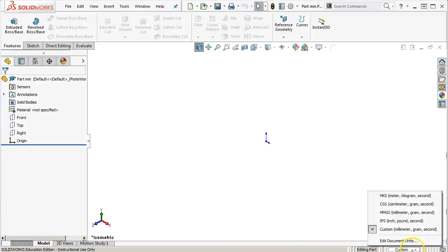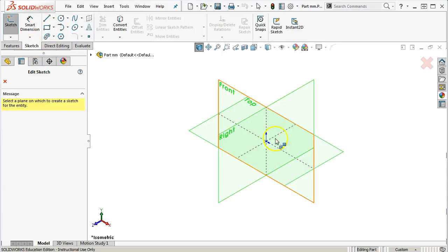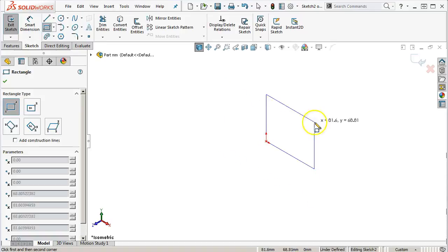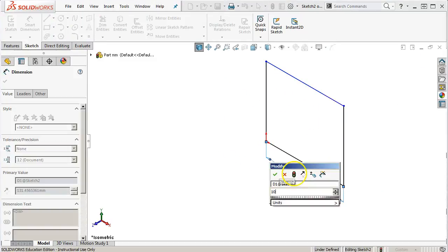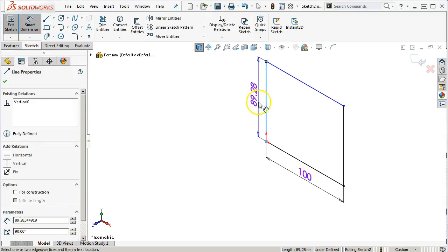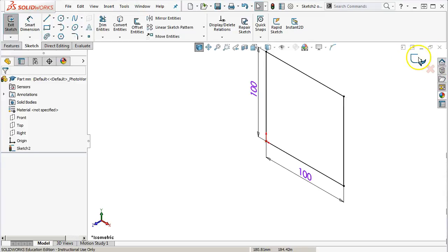At this point, I can go back. Now, the other thing of note is if I open up a sketch and I draw a box. Maybe I'm going to be drawing a lot of boxes, and I want to start with that box always in place, then I can open up a sketch, have my base dimensions in there, 100 by 100, and accept it.